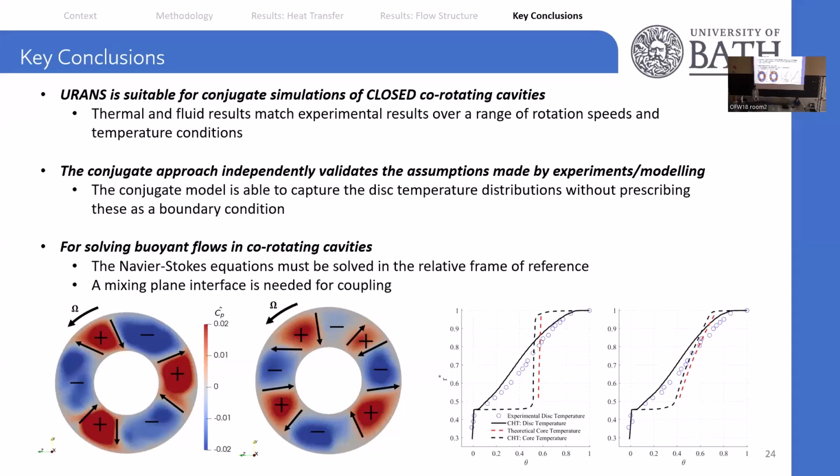Okay, so let's go to the time step. Yes, it's a transient simulation. We used an adaptable Courant number and kept it less than 1, but it was approximately 5 × 10⁻⁵ seconds for each time step. For the animation, you saw that. Yes, 10⁻⁵. It was a very fine time step. It's quite unsteady when it was first initialized.